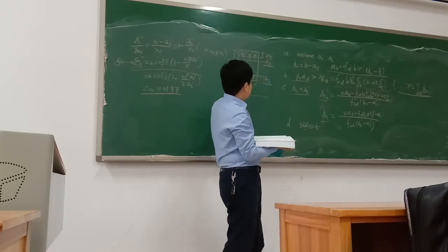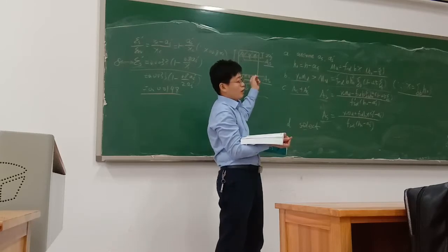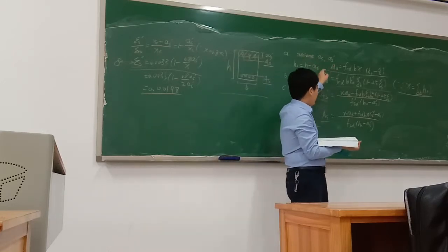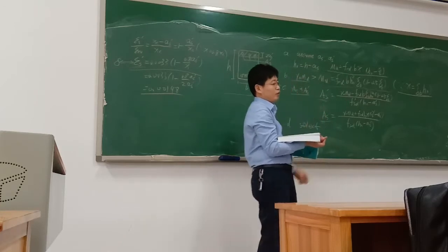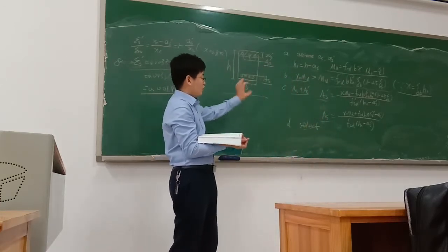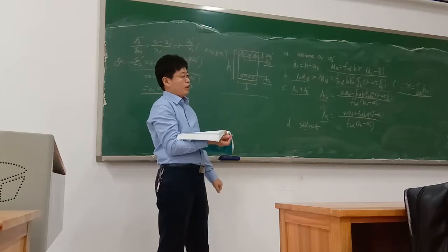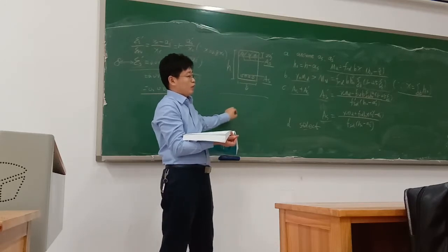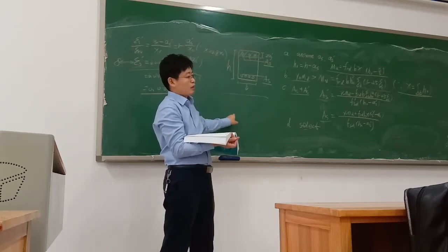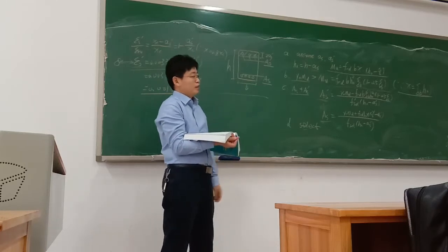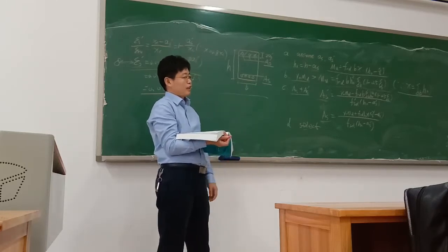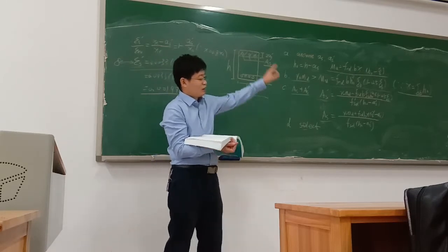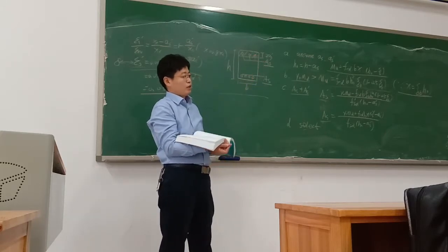Once you have determined the diameter and number of the steel bars, you get the real AS, AS prime and the area of the reinforcement. Then you use this real value to check the construction requirement and the resistance moment, Mu. If Mu is larger than gamma 0 Md, if this is satisfied, that means your design is okay. Otherwise, you need to go back, change the value and calculate again.